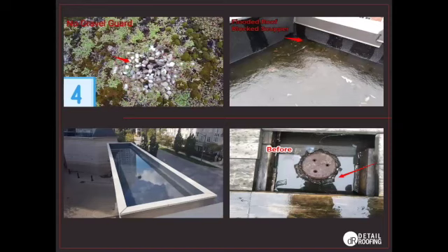Drainage can be a concern. Again, anyone familiar with our reports has probably seen us recommending gravel guards if there's gravel on the roof, or just clearing the drains, ensuring that they're free of debris. This is because if they become blocked with debris, they can create flooding or water ponding throughout the roof. If the membrane is in good condition, ponding water is not something you need to be too concerned about. However, if there are any openings, then that's just a place for the water to be getting in, traveling down, and creating a leak issue inside.